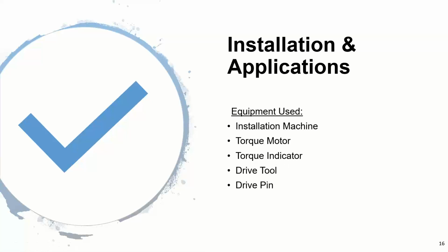For instance, I use ProDig. This is just one of the torque indicators out there. ProDig is a company in Kansas. I've been using them for the last 10 years. They're accurate to the foot-pound. And with all this high-tech, I connect to that torque indicator with my phone, and I can record all the installation from the beginning until the end. I can just email it to my computer and see the installation. I can record every 0.5 foot, or I can record every minute. It's really amazing. With this torque indicator, the one that I use, ProDig, it's very, very accurate.